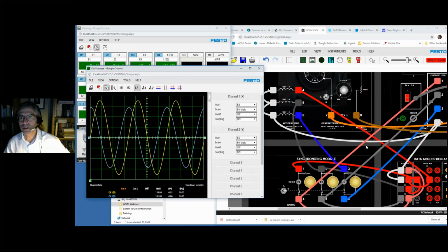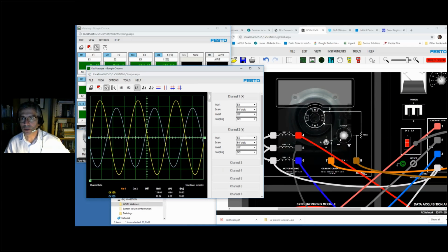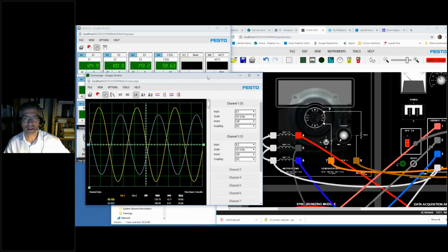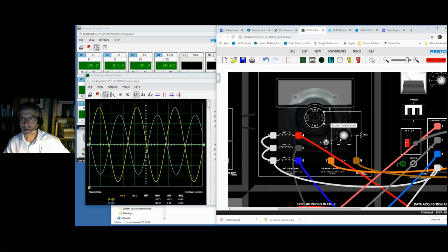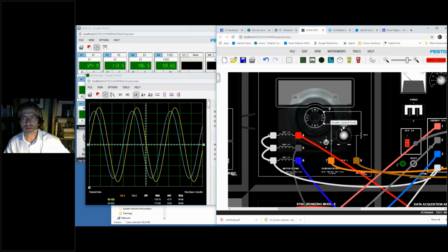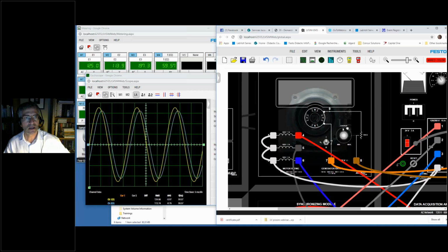We will need to increase the voltage produced by our generator, and we will do that by increasing the field here. So you will see that as I increase the field, the voltage output will increase. And you can see on the oscilloscope also that the amplitude of the voltage is increasing. So we increase that up to 125.